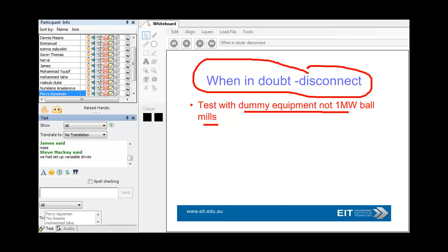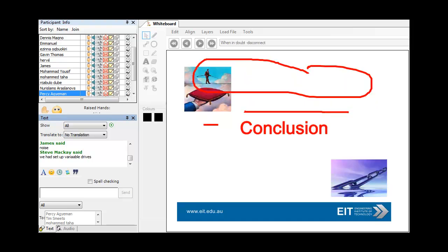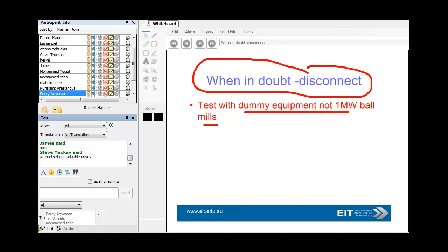So when our Japanese clients were being shown around the plant, our client said, look, I'll tell you what, I can't start the ball mill up, but I'm just going to show you the grease pump. I'm just going to push the button on the grease pump and that'll start it up. But he pushed the button and of course we had the ball mill start up at that point. So obviously major confusion. So if you've got any doubts about switching on pointers, make sure you check it out. But one point here again is make sure if you're doing any controlled analog or digital outputs, that you do give them a load to check your analog digital output cards.